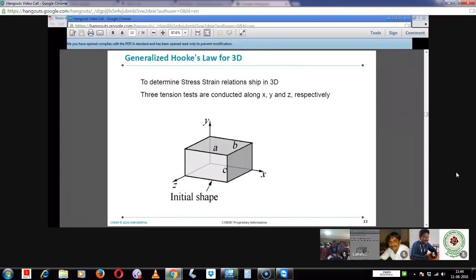And if our area of interest is the blade attachment or blade, then we need to go for a sector model. We need to take a simple single sector model and do the analysis. Here, similar to blades, these are also subjected to uniform pressure, uniform thermals, and angular velocities.